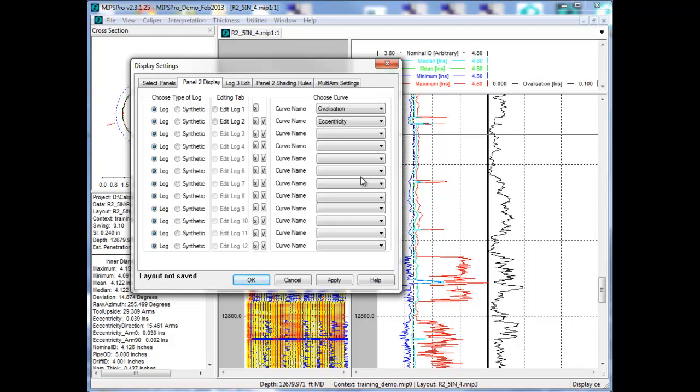The curve scale low and high values can be copied from the curve in the row above by clicking on the V. The curves will appear in the viewer when the Apply button is clicked. Curves can be removed from the layout definition by clicking on the cross. To set individual curve properties, select Edit Log and the third tab will update.